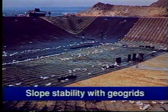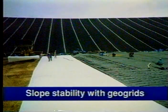As we've already indicated, the use of geogrids and other geosynthetics enables slopes to be made steeper and the capacity of the landfill to be increased. Multiple layers of geosynthetic materials may be placed on a slope. For instance, a composite geomembrane and soil secondary liner, a geonet for leakage detection, a primary geomembrane liner with a geonet for leachate collection, a geotextile filter, and a geogrid to support the soil veneer used to cover the lining system and prevent it from slippage.